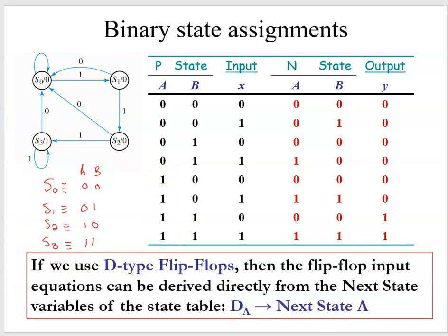So, that's what we've done so far. So we'll do that again. That's easy enough to do. We can make a Karnaugh map. We want to solve for the next state of A here, and we want to solve for the next state of B, and then we can also solve for Y. We can see Y is just going to be equal to AB, right? That's when we're in our present state 3.